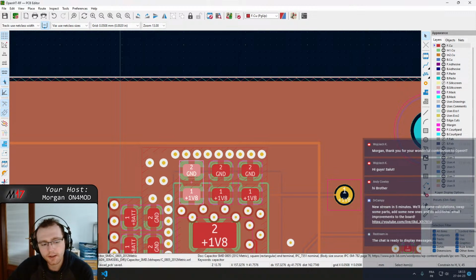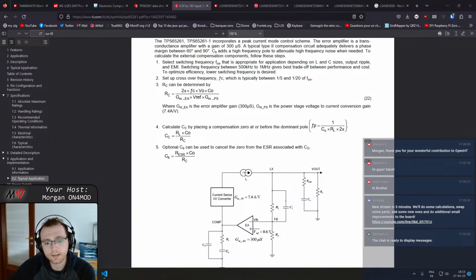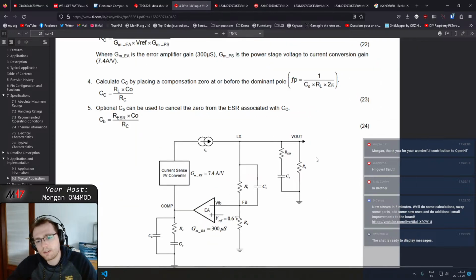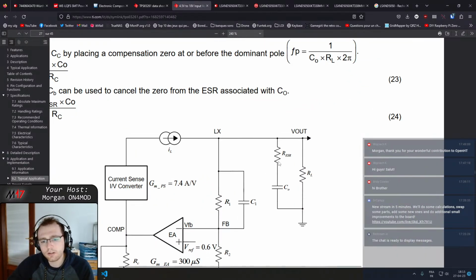Ceramic capacitors are nice because they don't age like the electrolytic capacitors, which can dry out and then the value of the capacitance is going to change and so on. So that's one of the reasons that we like ceramic capacitors. One of their other characteristics is that they have very, very low series resistance. The RESR here is not a real component on the board.